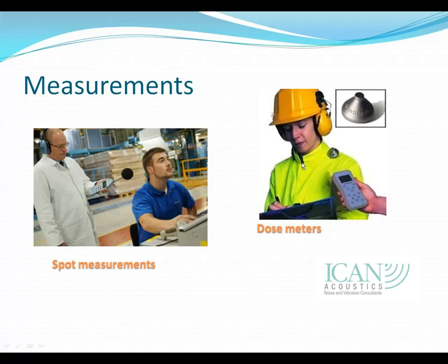For example, they become a measurement technique that's carried around in the absence of any sort of supervisor, if you like. So they could be, for example, left in cloakrooms. You just don't know. They're an unattended measurement, so you're trying to determine the noise exposure, and you don't know much about where the employee has been. So again, spot measurement technique would be favoured in terms of an operator being able to quantify what the employee was doing at that time, or the machine that was being used, and so on.